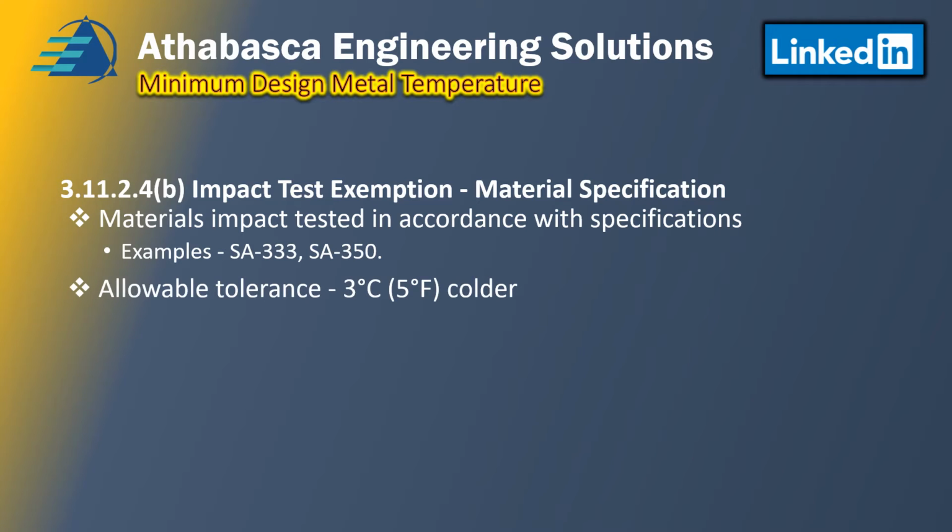Another thing that's available is the allowable tolerance of minus 3 degrees centigrade or 5 degrees Fahrenheit colder than the published value. You can take advantage of the tolerances to get another few degrees, because of the error in the data that's provided, and that may give you what you need if you're very close. And this is all identical to Section 8, Division 1, UCS 66G.